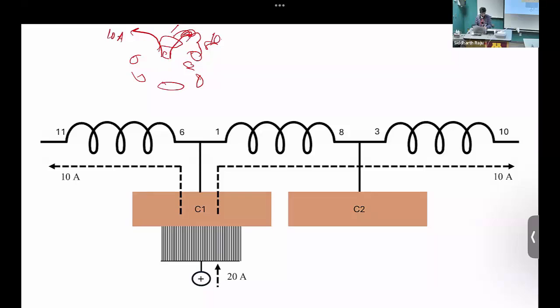On the right, 10 ampere went through it, for a total of 20 ampere coming out of the coil, of the brush. So 20 ampere coming here, and it's splitting into two pathways, one going to the left, one going to the right. Right, everybody clear? This does not come out of this path because this commutator is hanging, it's not connected to the external world. C4 is the one that's connected to the external world. So this 10 ampere flows to the three coils and then comes out of C4.